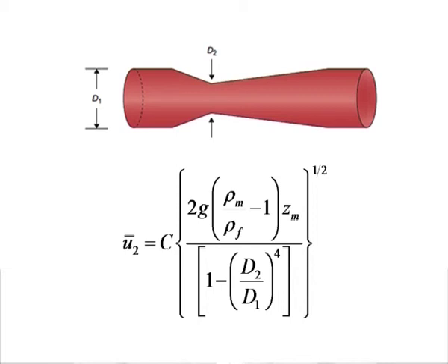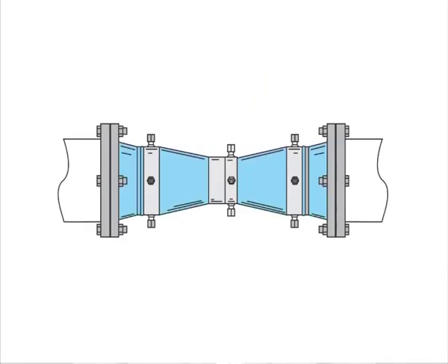The Venturi meter requires careful construction to ensure proper angles of entrance to and exit from the Venturi. The meter requires a significant length of pipe for installation compared with the orifice meter. In general, the orifice meter is less costly and simpler to design than the Venturi meter. However, there are certain advantages using Venturi meter in the industrial scale. Some of them are as follows.